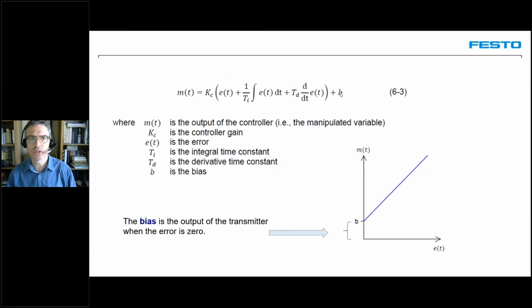All of these parameters are set together inside the control equation, as we can see here. So the manipulated variable, let's say once again, our pump speed, will be equal to the sum of all these parameters if we are in PID control. So P here, I here, and D here. You can see in this equation that our controller gain is right at the start of the whole equation, and multiplies each of these terms. So each term is multiplied by the controller gain.